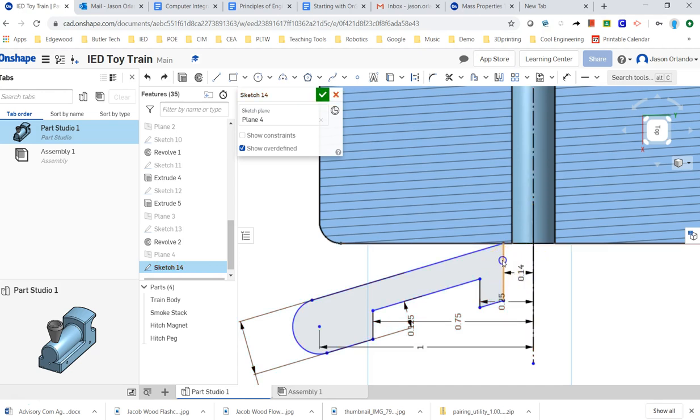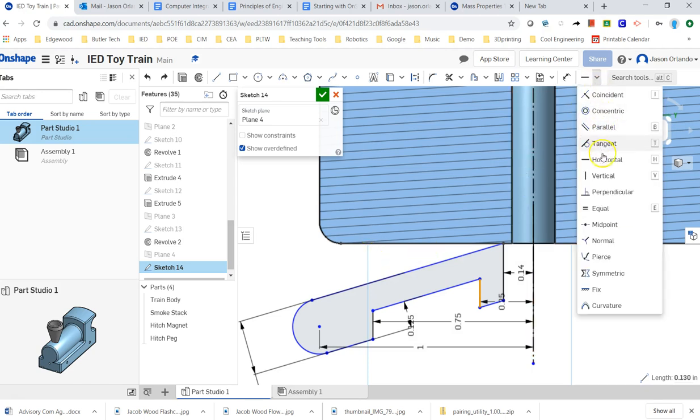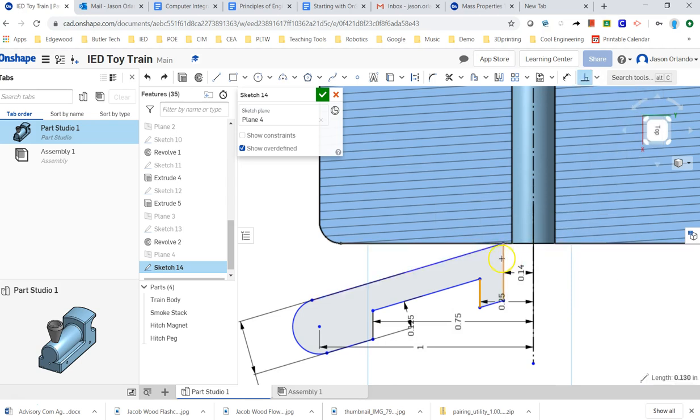And I'm going to hover here, or click on, let's see, what constraints do I have? There. Okay, so the orientation I'm in, that's what I was thinking. If I hover over that line segment, or click on the line, I can see geometric constraints that are there. And so this line is, it's going away on me, but hopefully you can see that's showing parallel and horizontal. But that looks vertical on our screen, right? So I actually need to use the vertical constraint to get it to move the way I want. Or another option would be even just to go use the perpendicular constraint if I've got this one the way I want.